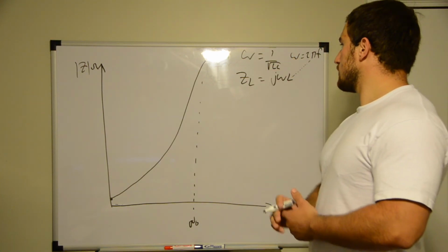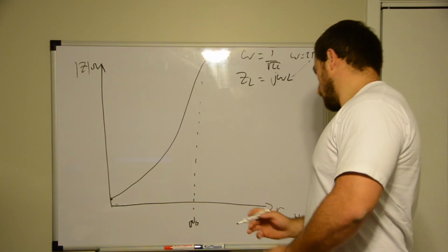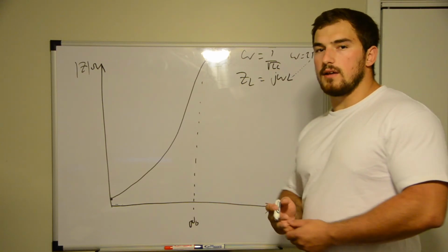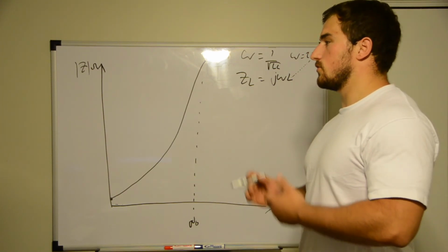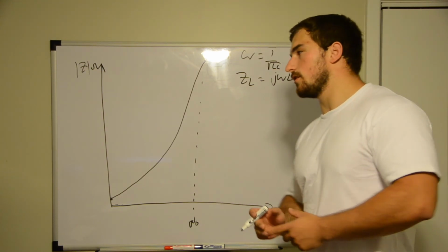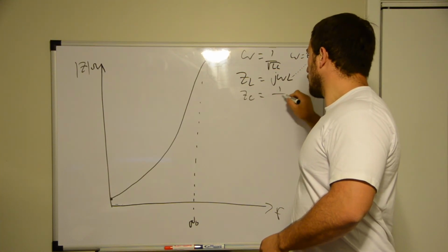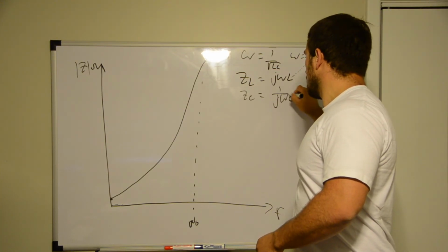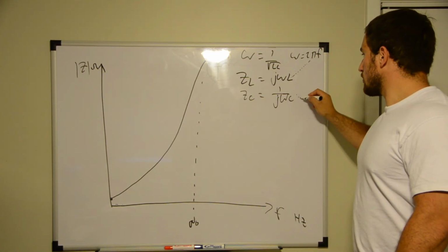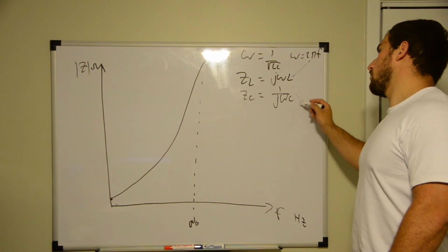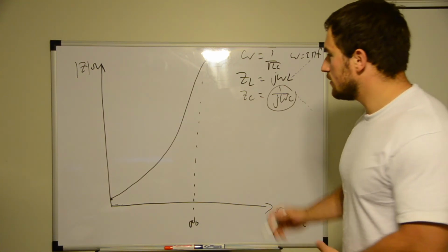And after that, what's it going to do? That's when we start seeing it go into high frequencies. And we found out that the capacitance effect dominates the inductor, so it begins acting like a capacitor. So the impedance of a capacitor equals 1 over j omega C. As frequency keeps going up and up, this should eventually go down to 0 because it's basically going to act like a short, zero impedance.